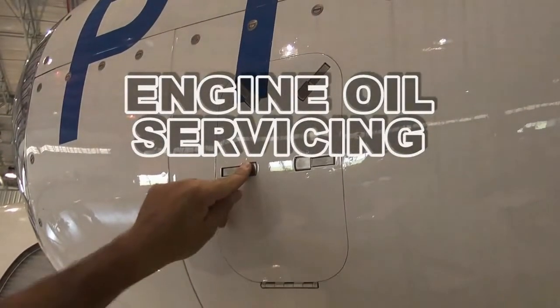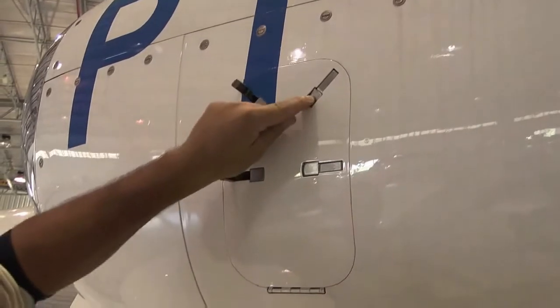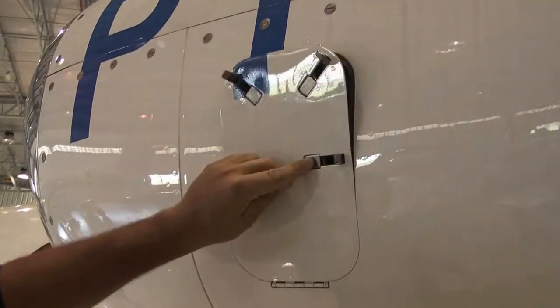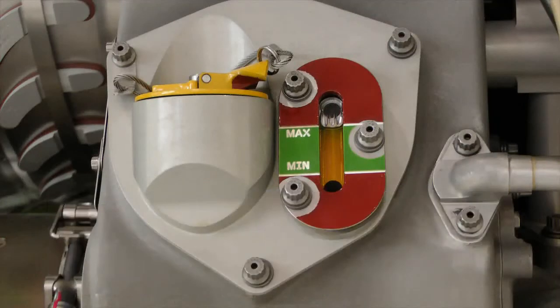Engine oil servicing. The engine oil is checked as necessary. To check the level, open the proper access cover and check the side glass. Check the indication between minimum and maximum marks and refer to the table.